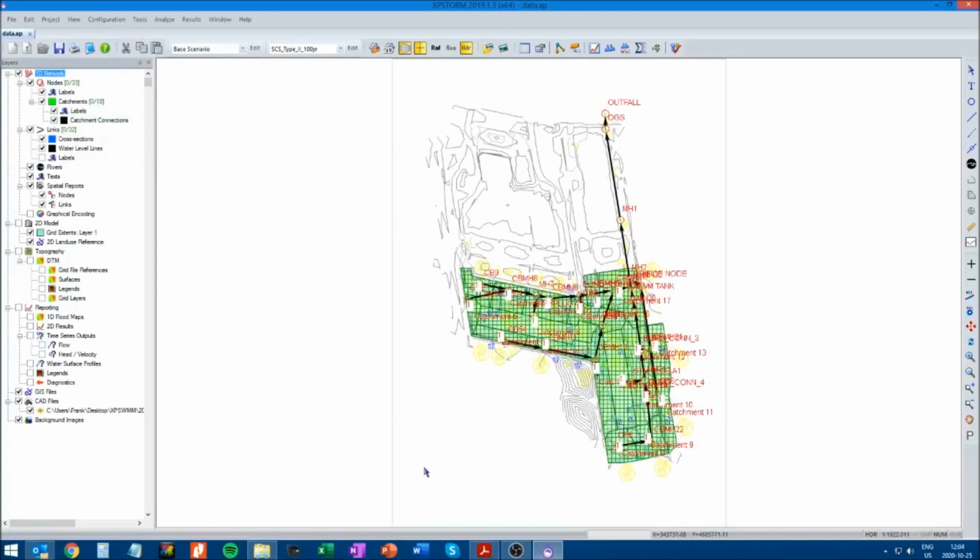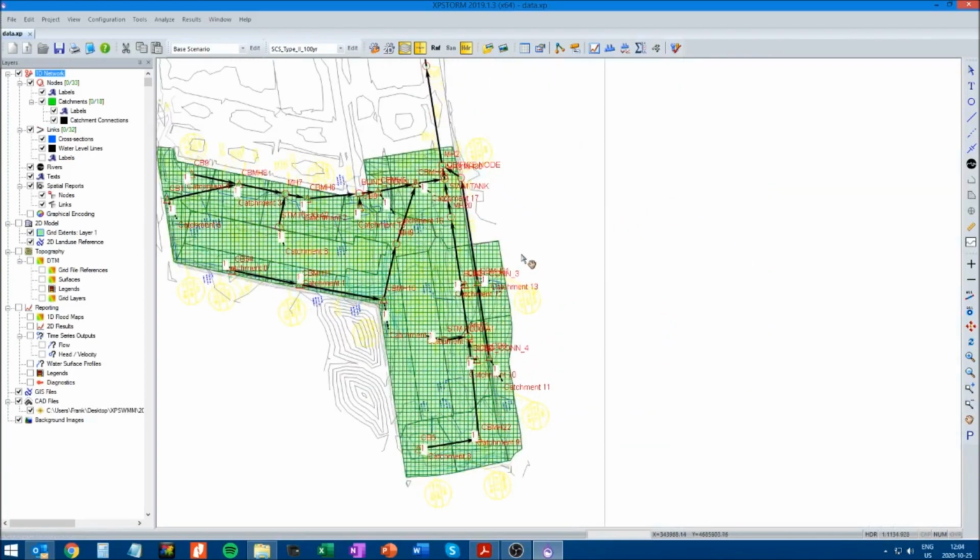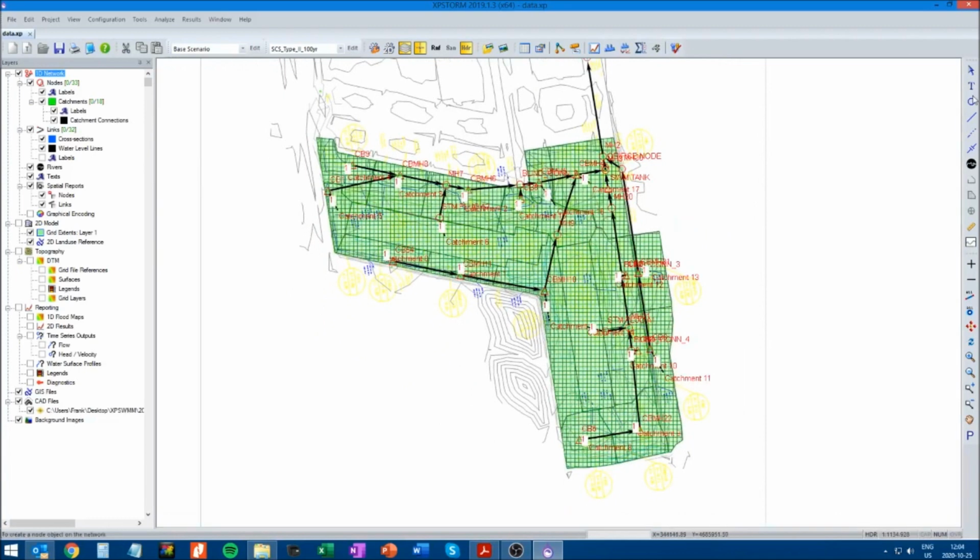When I was sizing the underground storage, I sized it based on whether or not there was overflow at the individual catch basins. To optimize the sizing, we can actually let the catch basin spill from one catchment area to the other.